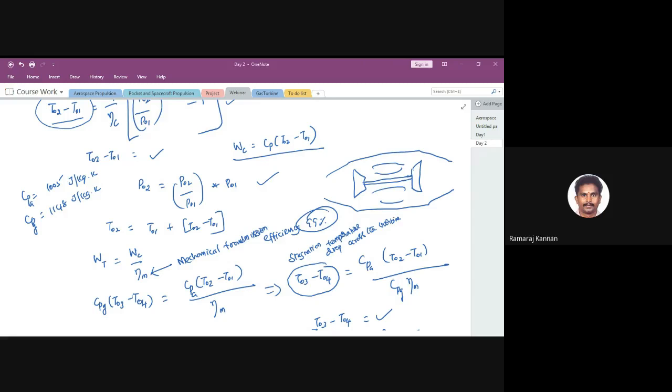Then, they are going to give an input parameter as the turbine rated temperature. We know the isentropic efficiency of the turbine. So if the process is treated as isentropic, what is your stagnation temperature drop? From that we can calculate how much stagnation pressure there is at the exit of your turbine. Then we know that the nozzle exits into the atmosphere where your pressure is PA. From that we will see the nozzle pressure ratio, that is your P04 by PA.